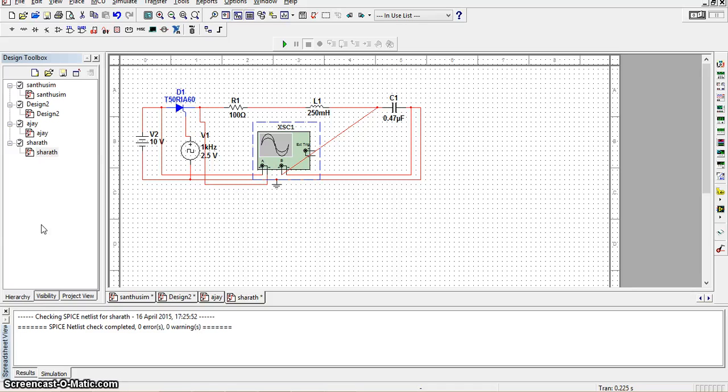Third, anode current flows and charges up the capacitor. The RLC forms a second order underdamped circuit. The current through the SCR builds up and completes a half cycle. The inductor current will then attempt to flow through the SCR in the reverse direction and the SCR will turn off. The capacitor voltage is at its peak value when the SCR turns off, and the capacitor discharges into the resistance in an exponential manner. The SCR is reverse biased till the capacitor voltage returns to the level of the supply voltage V.